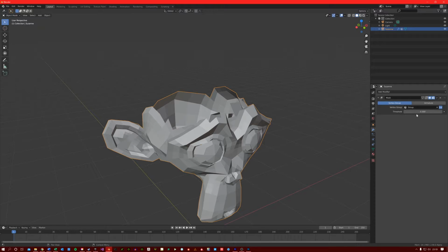And lastly, the threshold value here is linked to mesh weighting. Vertices with weights less or equal to this threshold will be hidden. Weights can be customized using the weight painting feature in Blender. So when can the mask modifier be useful? A good example is if you want to mask off a character's body and then place clothes over them. The mask modifier will prevent the body and clothes clipping into each other.